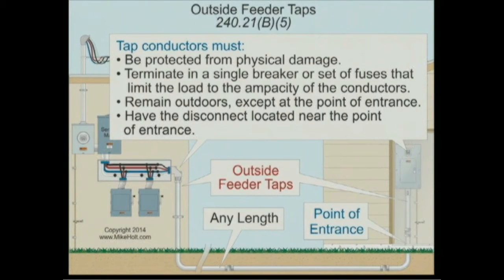Brian? Well, I was talking with Ryan earlier, and correct me if I'm wrong, but it seems like a great use for this would be exactly what you're showing here when you're feeding a panel in an outbuilding or whatever, and you don't have any spaces left in your feed-through panel. You can use the feed-through lugs on the bottom of the panel that's got a 200 amp main and put a 100 amp main in your outbuilding, and you're good to go.